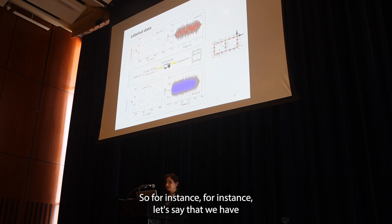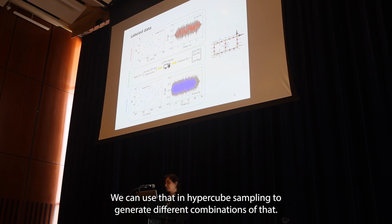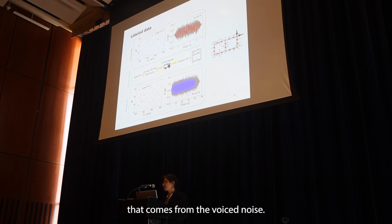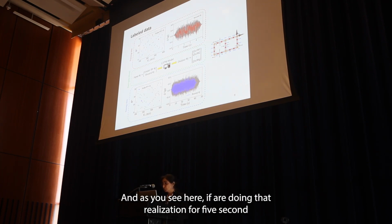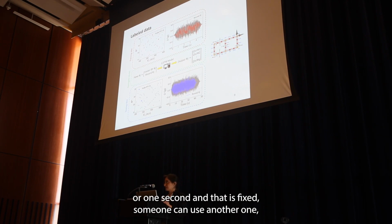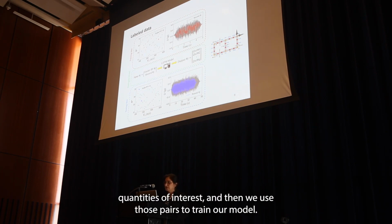Here I'm showing how we generate our labeled data. For instance, let's say that we have the angle of incidence and the shear wave velocity as random variables. We can use Latin hypercube sampling to generate different combinations of them. For each combination, we pair it with one realization from the white noise, and as you see here, we generate that realization for 5 seconds, with a sampling rate of 0.01 second, and that is fixed. Someone can use another one. Then for each of them, we run the finite element, we generate our quantities of interest, and then we use those pairs to train our model.